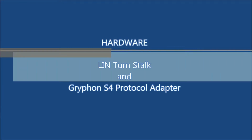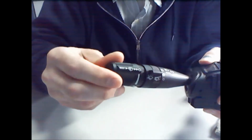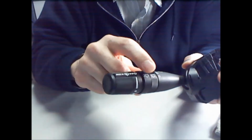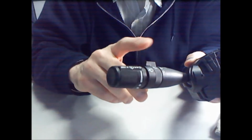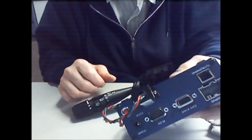Let's take a look at the actual hardware that we will use for this demo. The LIN device is a turn-signal stalk. It has right and left turn switches. It also has intermittent wiper controls for the front and back wipers, washer controls, and headlight high beam controls. As we change these controls, the LIN device outputs new data on its next response to the LIN master. The Gryphon S4 protocol adapter connects to the LIN device through an optional plug-in LIN card. The Hercules software that runs on the PC communicates to the Gryphon over Ethernet.